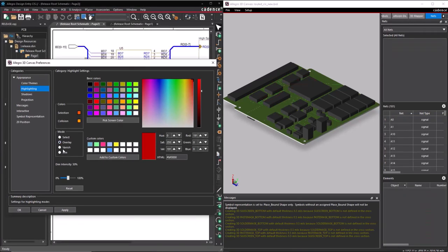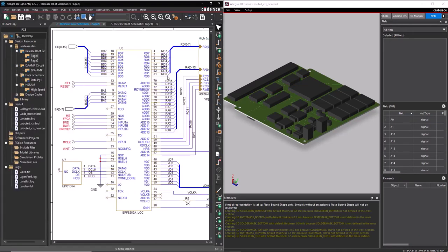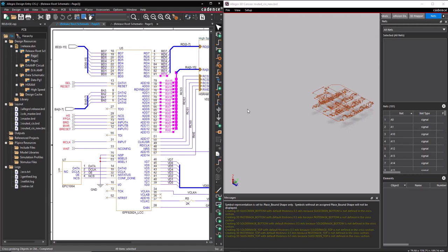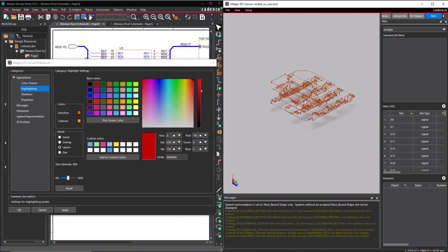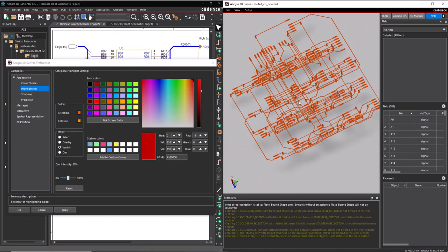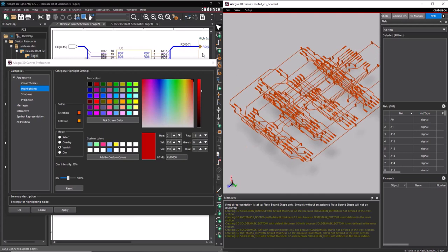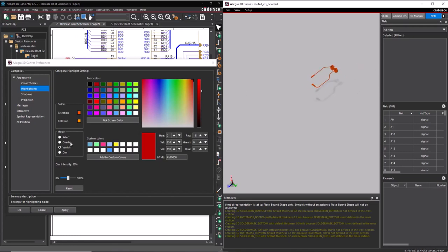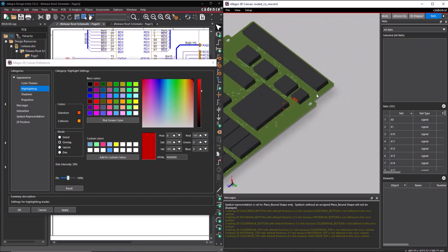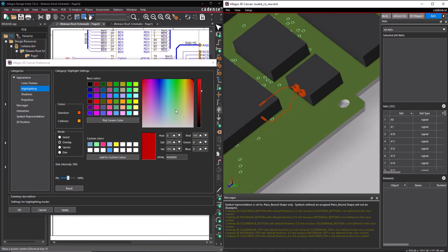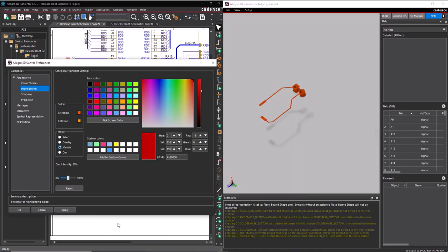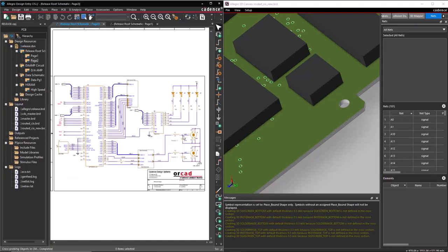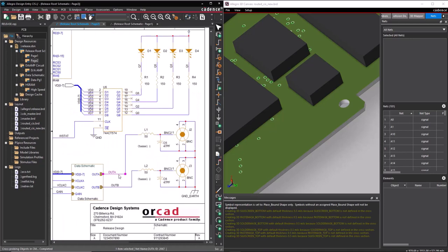The other mode you can view the net is the Vanish mode. Select the Vanish mode, and if you choose the net from the Allegro Design Entry CIS, you can view only the selected nets and their vias in the 3D Canvas. To see how particular nets are routed in the design, you can alternatively use Vanish and Overlay mode. The nets belong to data, and the clock is selected to show in this fashion. Similarly, the net belonging to output is seen here.